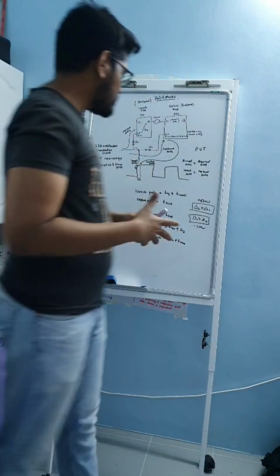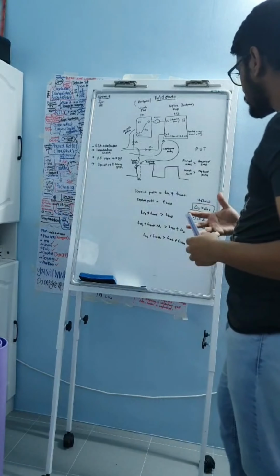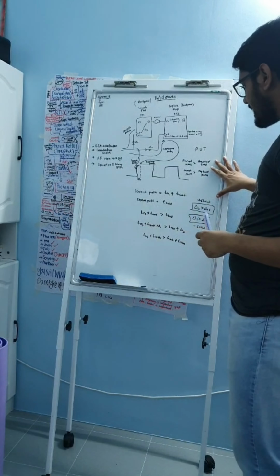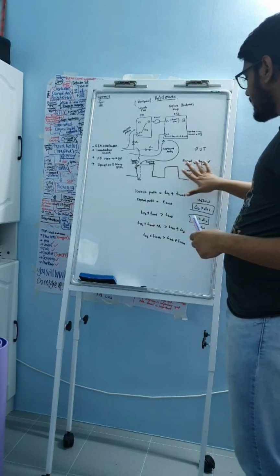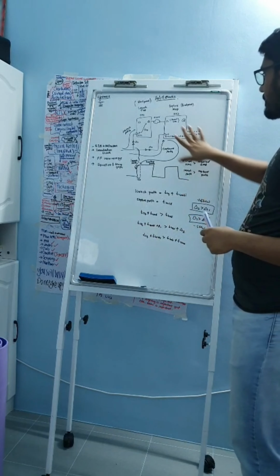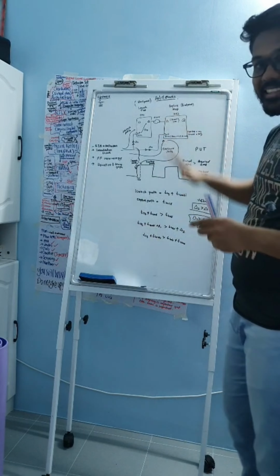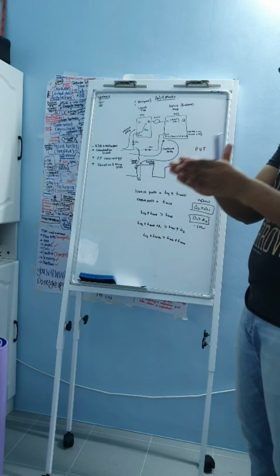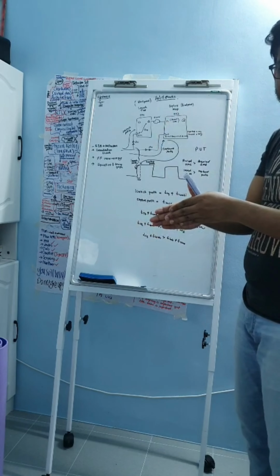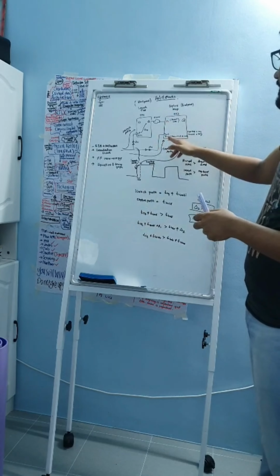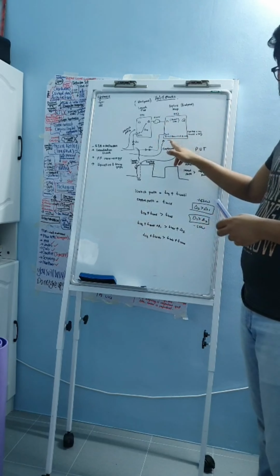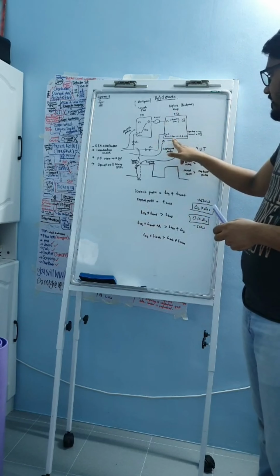The whole picture everyone has to understand is making sure that the arrival time has to be more than the required time, because the data has to be stable for an amount of time after the required time.